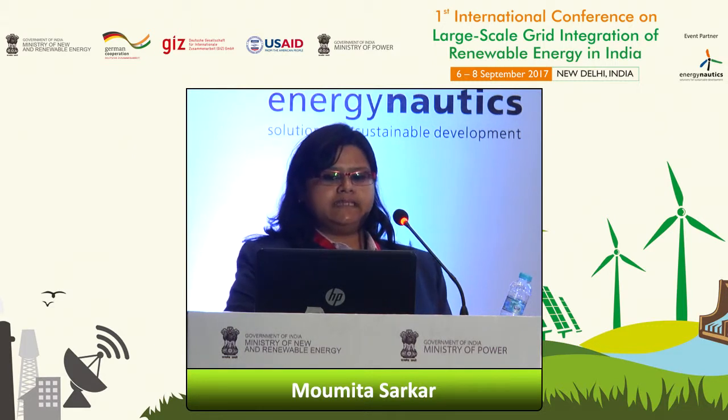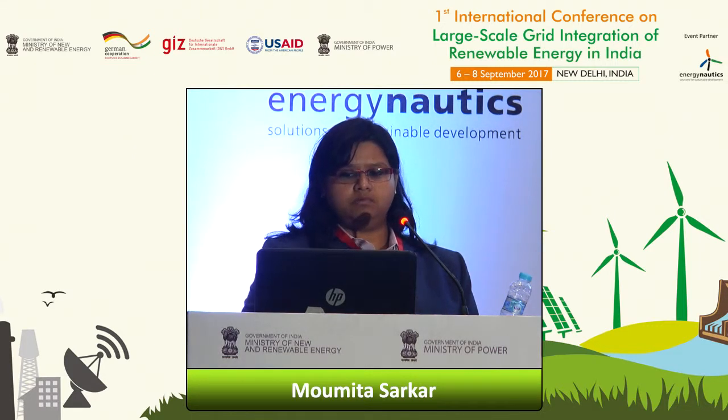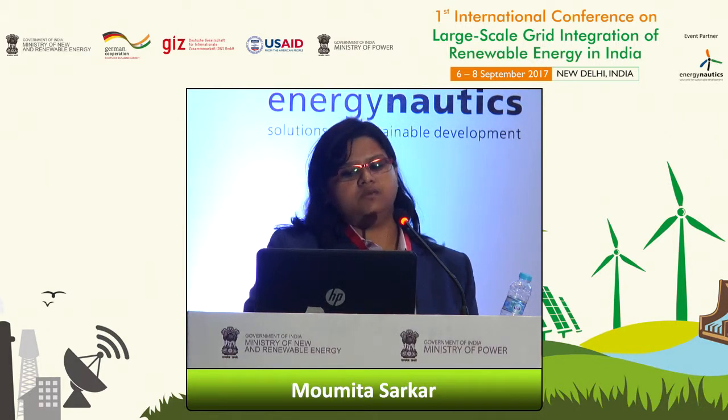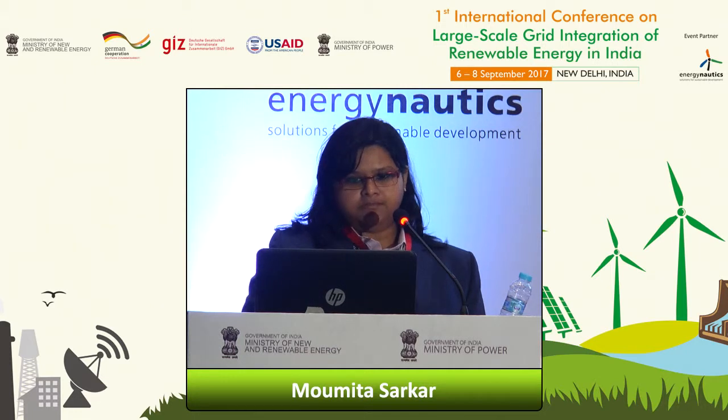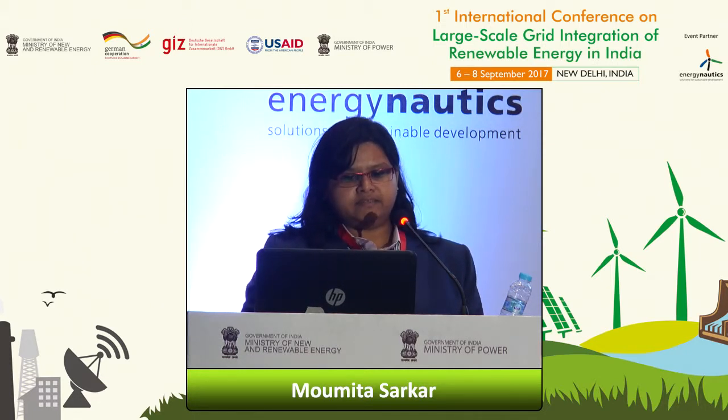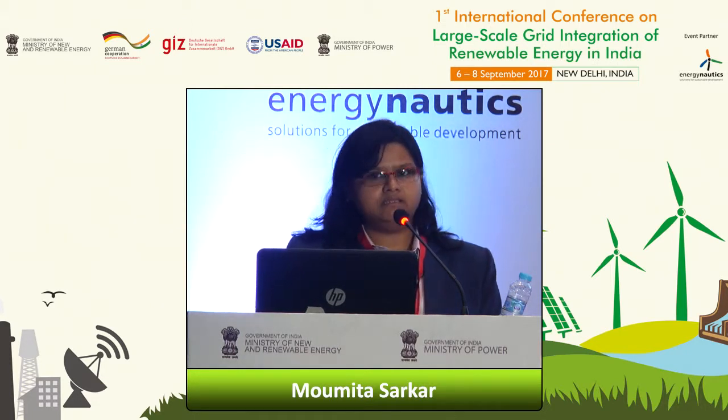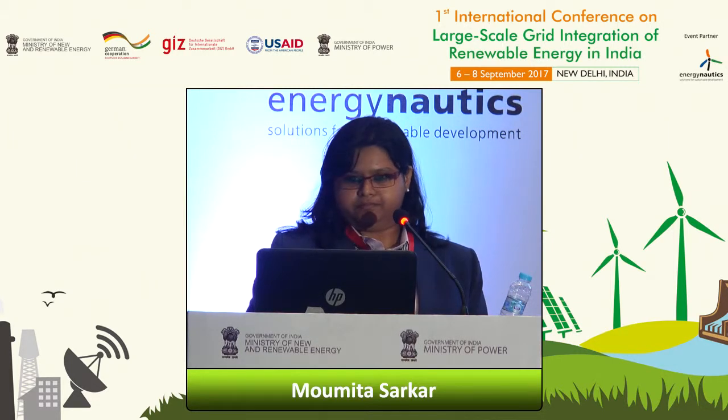Next comes the static generator block. This is also similar to the IEC model, and we have implemented a current limiter model along with a phase lock loop and a static generator block. The inputs to the generator are the reference active and reactive currents and the PLL information.